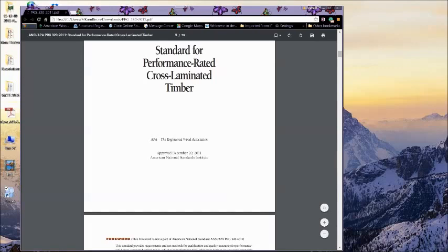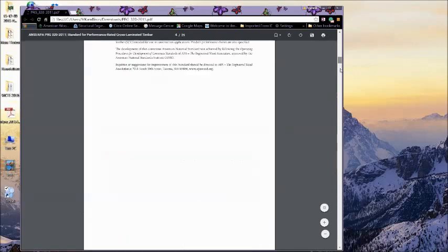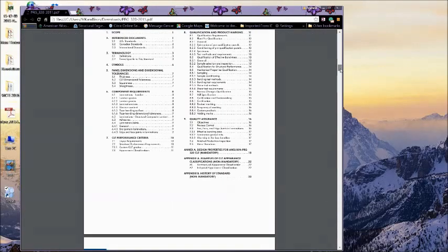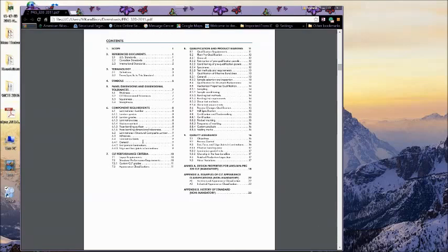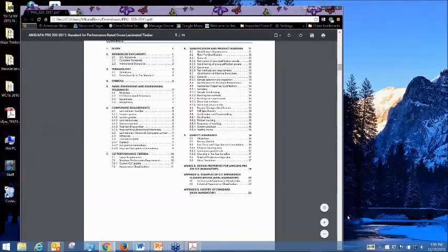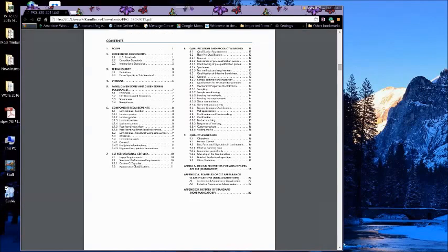We're still right in the midst of research on those products, and it is a very long process to get R factors developed for shear walls. So designers and code officials need to discuss that to make sure they're on the same page with any CLT panels used in seismic shear applications.